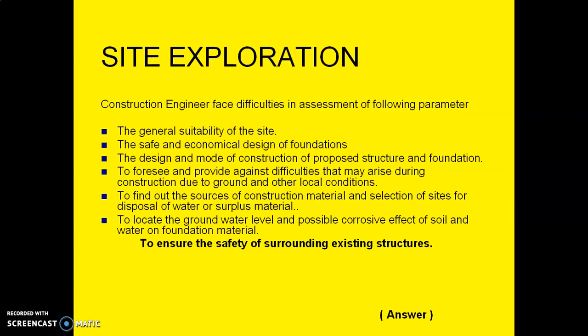The knowledge about the site forms a vital role in the safe and economical development of a site. Public building officials require soil data together with the recommendation of a geotechnical consultant prior to the issuance of a building permit. Elimination of site exploration leads to false economy of redesigning the structure.